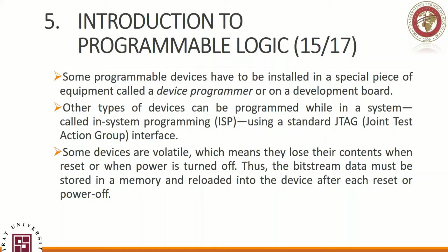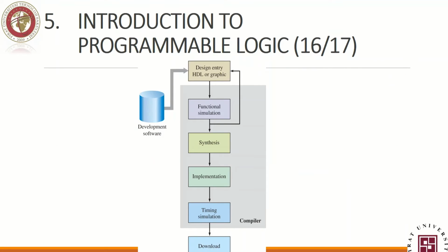You say simply because some of them have a volatile memory design, so they lose whatever content they have when the power goes off, and once they lose that programming functionality or the program that they have in them, they become useless. And in order for us to reprogram them, we don't need to do that every time. Instead of that, we have an attached ROM or an attached memory that loads this program when the power goes on. Okay. So this is the schematic diagram of the programming process.